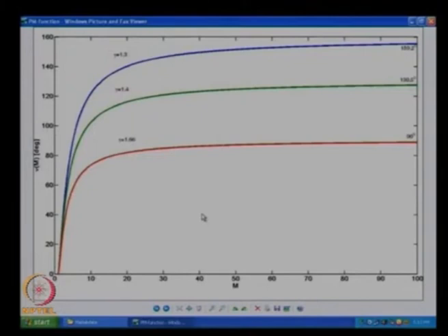Okay. We did that particular example for M tending to infinity last time, and we found that for gamma equal to 1.66 it just turned 90 degrees and stopped, while in the other cases it went farther. Basically it is going to the same Mach number, but it is filling more space. It is more expandable, similar to looking at a more compressible gas. Okay. That's one way of looking at things.